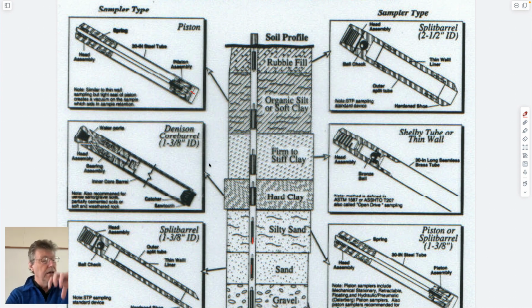For clays, they're always so-called thin tubes. They're always pushed into the bottom of the hole just by using the drill rod in the hole, putting a weight on it by the drill rig and putting it down, usually 18 inches or 2 feet, which is the length of this. Twist it, pull it out, and take the sample to the surface, and receive it.